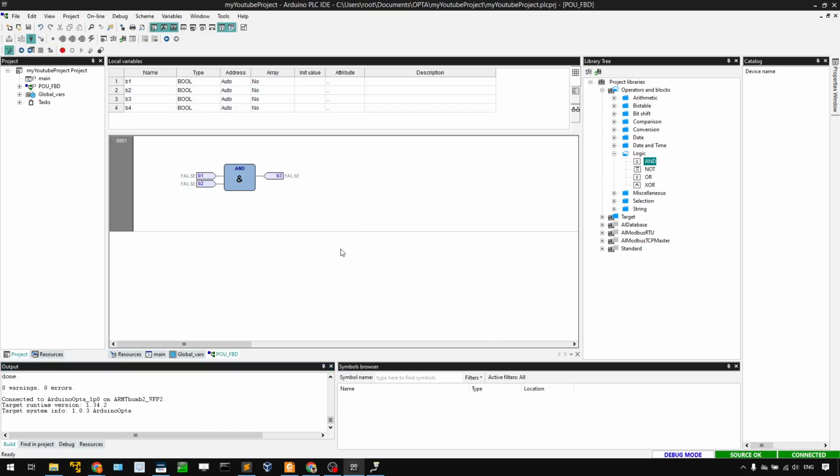And click online again. Now you can see here false, false, false, because we don't have any initialized value, so the default value is false. Now we can just double click here. You can directly change the value of your variables to any values. In my case, for example, I can change it to false or true, and just +1.